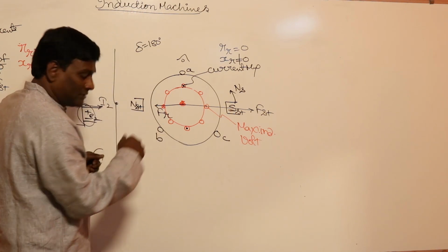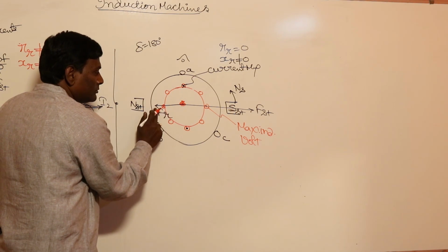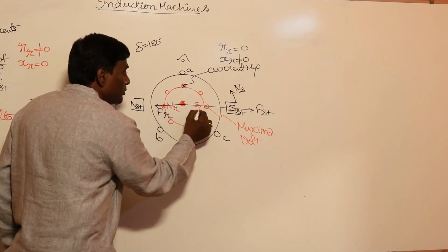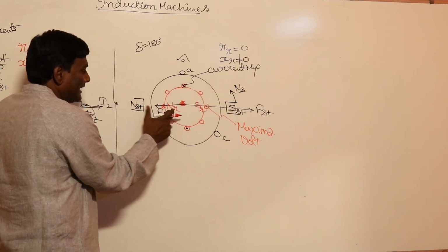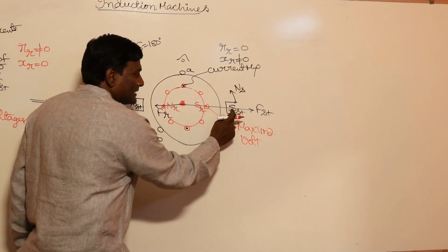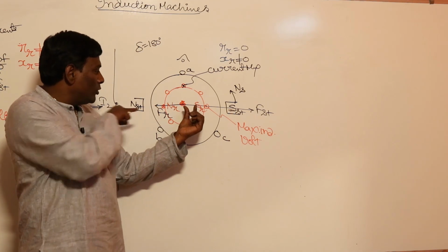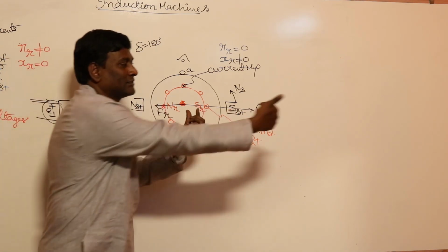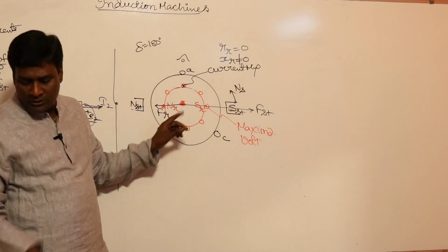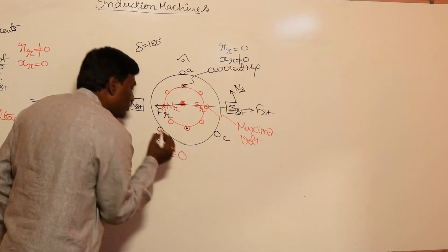But now, for example, if I think of the rotor, my rotor flux is coming out. You are sitting in the air gap, so this should be the N pole of the rotor, this should be the S pole of the rotor. So at N, repulsion will be in this direction, at S, repulsion will be in this direction. You are sitting at the shaft. Some torque is pushing in this direction, some torque is pushing in this direction. What is the net resultant torque appearing here? 0. So in this case the electromagnetic torque developed is going to be 0.